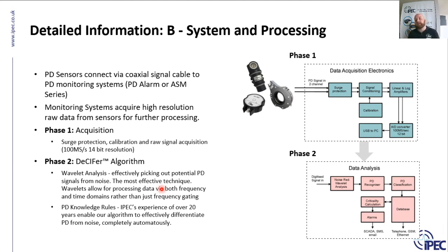A wavelet analysis is a time and frequency based analysis. As the system is processing the data, it preserves the time-based information at the same time as analyzing the frequency changes in the signal. It looks at the time and frequency domain, progressively assessing the signals, so with very large background noise and very small PDs, the system is very effective at picking out these small PDs, and it can preserve the information of the PD.